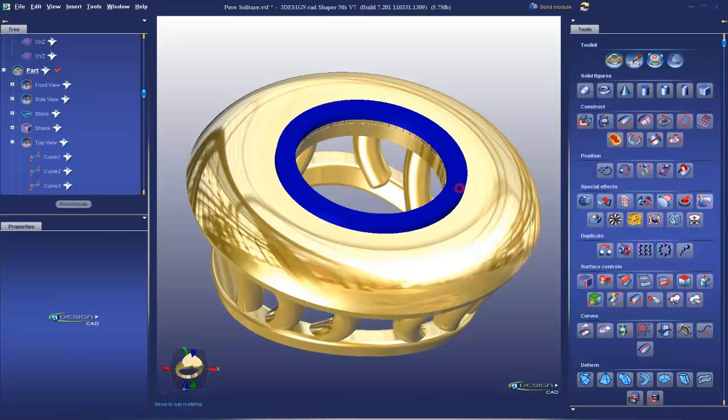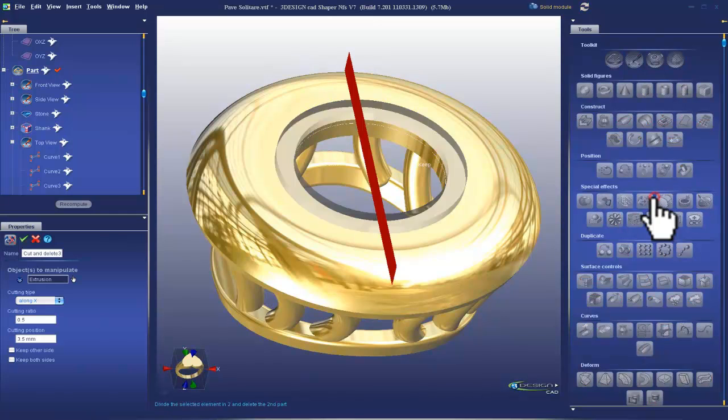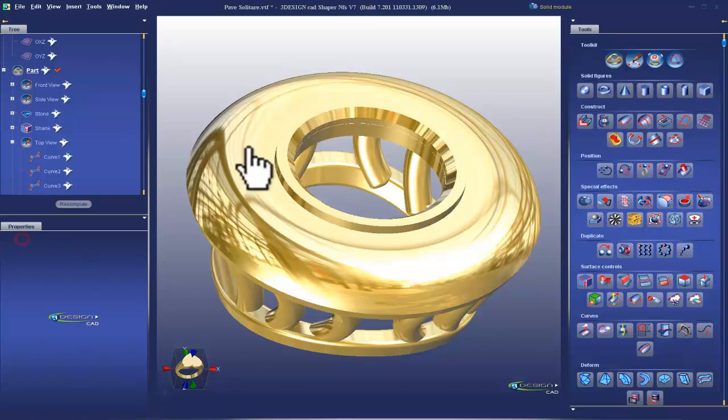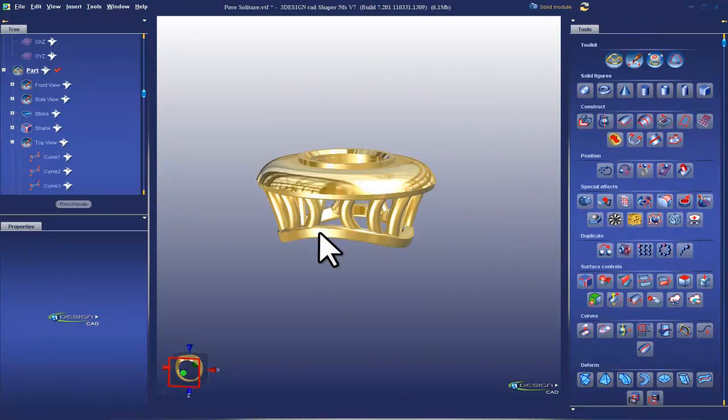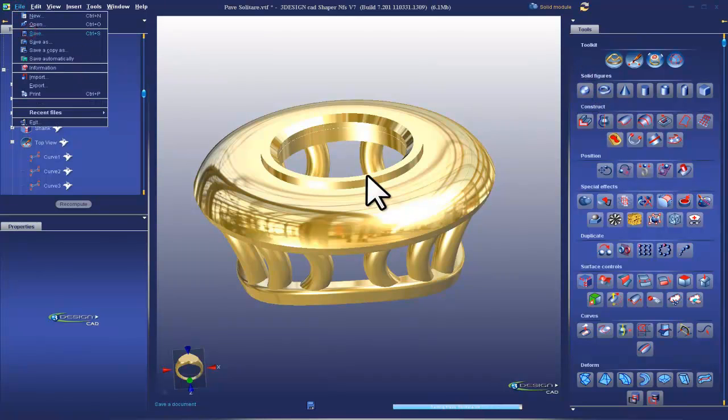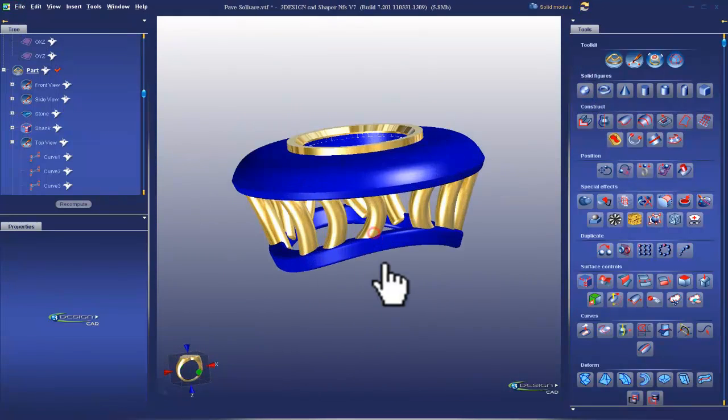And last thing I want to do is add a chamfer, which is like a fillet, but it has an angle. I'm going to add a chamfer to that inner corner. Let's do 0.3 chamfer, and it'll just cut it like there. Nice. So save, and Boolean.